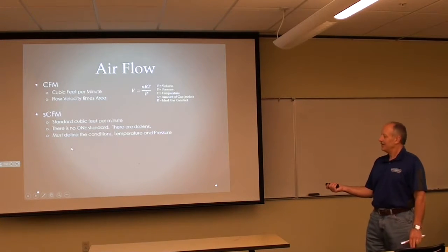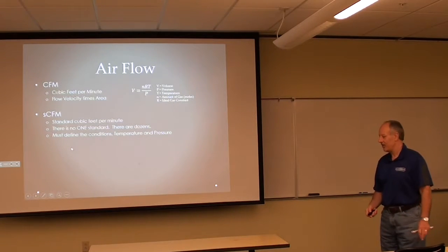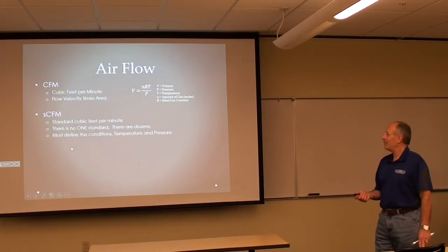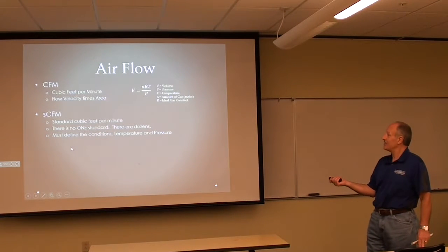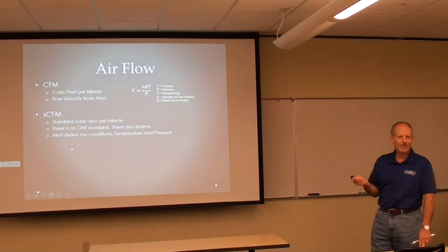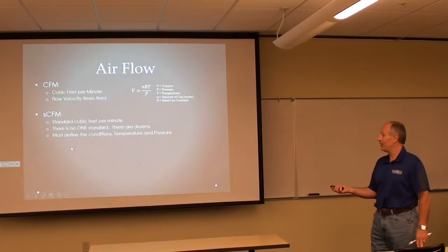And you also talk about a thing called standard cubic feet per minute. It's a big thing in industry. One thing that I learned after I got into it, when I started doing this presentation, was there's not one standard for standard cubic feet per minute. I didn't know that. Everybody has their own standard, so make sure you ask what standard you're using if you're going to use standard cubic feet per minute.